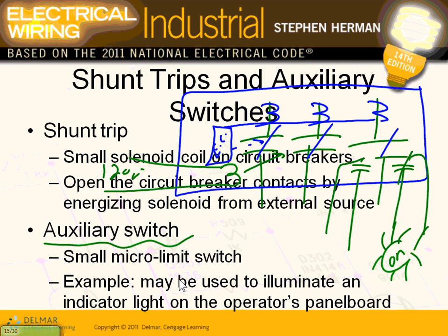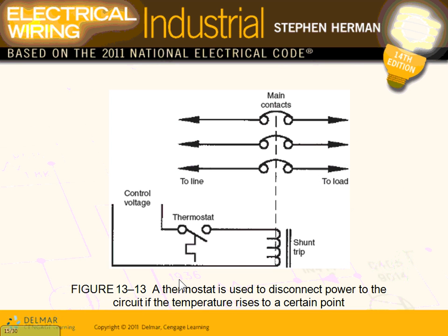So if you go to work somewhere else, Dustin, and they say shunt trip on the elevator, when we do a fire alarm system, if there's a fire on this floor, it's supposed to send a signal to the elevator circuit breaker or controller and open and shut down the elevator, bring it to a certain level, shut it down. So how are you going to get a signal like this to interface through the shunt trip? Very, very important, the shunt trip business.